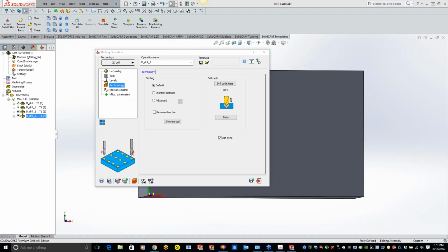I know that some of those older machines, as weird as it sounds, you can actually choose whether or not to use a G cycle. So maybe we can look a little bit further into the controller and see if there's a parameter setting that might be changeable in order to take advantage of cycles.